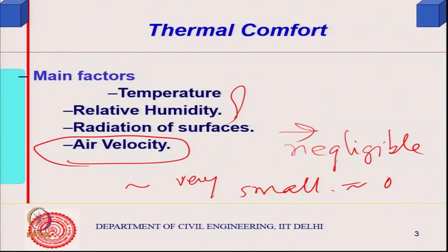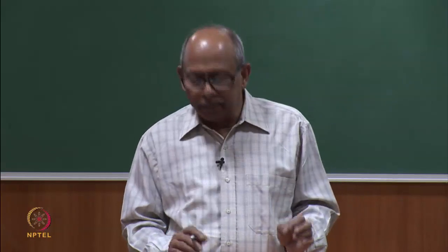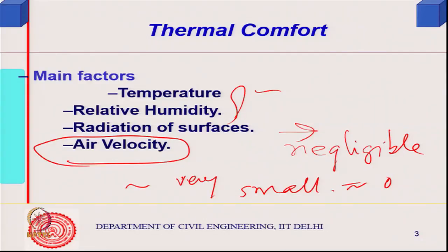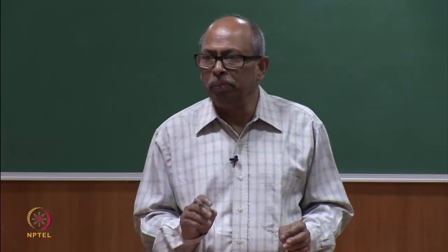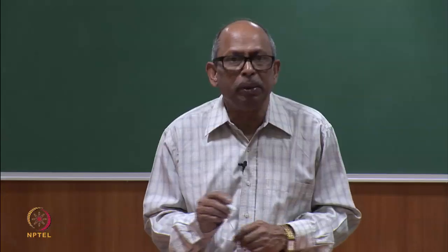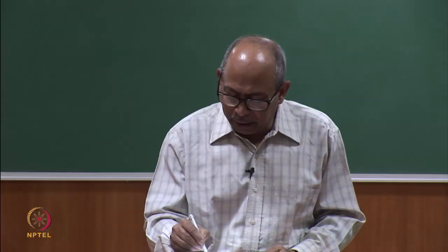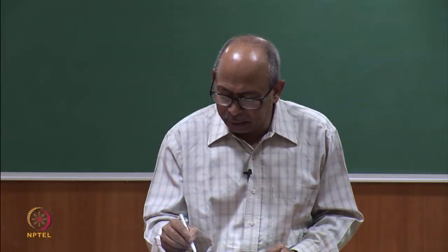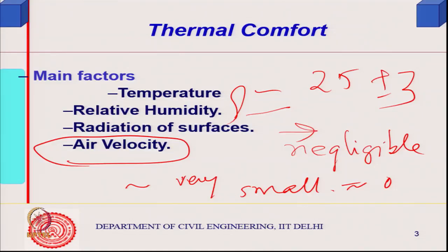So, for air conditioning, the desirable values of temperature and relative humidity plus the operating differential, that is what we consider. So, that is what we maintain. Suppose in the Indian scenario, you would like to maintain 25 degrees centigrade plus minus 2 or 3, and relative humidity of 60 or 65 percent plus minus some percentage.